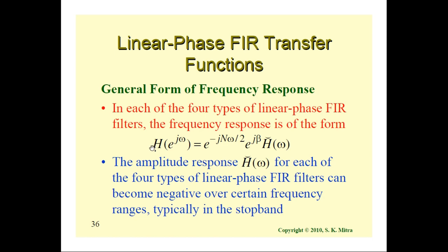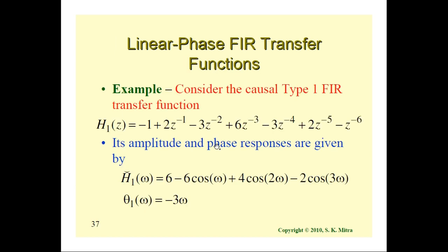So in all four cases, we have noticed that the generalized frequency response is written as a product of the phase response term times the amplitude response, where the phase function is always equal to N omega by 2, which is a linear function of omega.